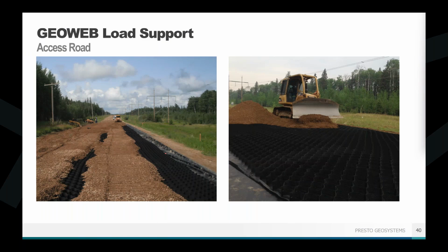If you have some very heavy loads, such as reach stackers, if you're in maybe a port environment, having a thicker wear surface, maybe 4 or 5 inches, is going to be a little more applicable. If you're on a residential road or a low impact road, something you're not going to drive on very frequently, you could go as low as 1 inch. So pretty wide variation, and we can help you determine what that's going to be.